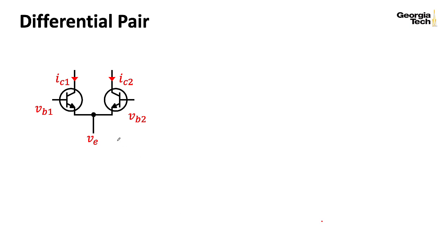So the trick we're going to use is to use a pair of transistors. We may not know what their characteristics are, but we're going to suppose that their characteristics are the same. Ideally, these are built on the same die, so there are two transistors right next to each other, and they're going to be thermally coupled so that their characteristics will change in tandem with temperature.